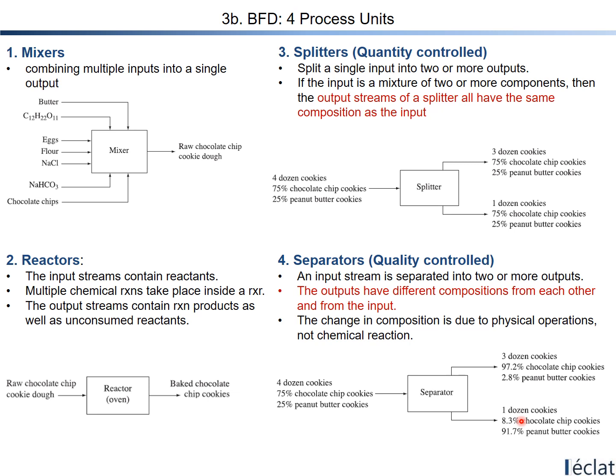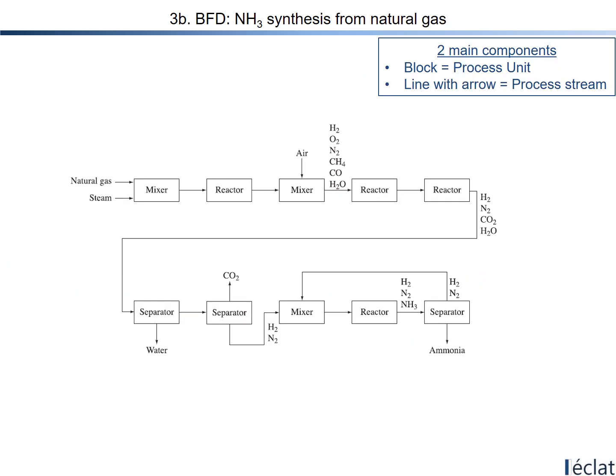However, splitters can touch the amount but not compositions. Please try to understand how to distinguish between splitters and separators. Anyway, we have these 4 process units which are used in describing block flow diagrams. Okay, so this is one example of a complete block flow diagram.